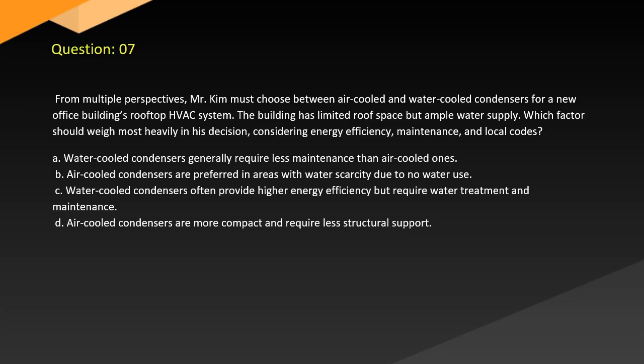A. Water-cooled condensers generally require less maintenance than air-cooled ones. B. Air-cooled condensers are preferred in areas with water scarcity due to no water use. C. Water-cooled condensers often provide higher energy efficiency but require water treatment and maintenance. D. Air-cooled condensers are more compact and require less structural support.